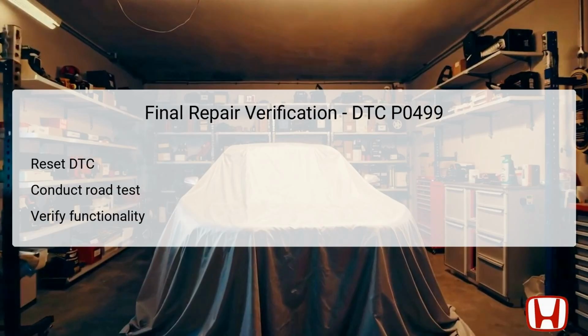After repairs have been made for DTC P0499, it is imperative to verify that the repairs successfully resolve the issue. The first step in this verification process is to reset the diagnostic trouble code DTC using the Honda Diagnostic System HDS. Following the reset, a comprehensive road test of the vehicle should be conducted to ensure that everything operates smoothly.